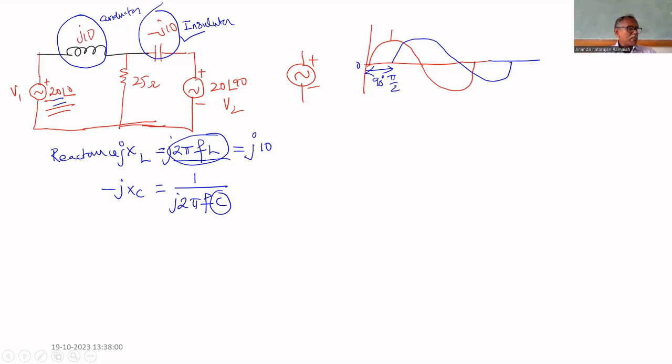Resistance, you know, will resist the flow of current. For AC, its behavior is also like resistance. A pure inductor means there will be a phase shift, a lagging current. A capacitor means there will be a leading current. But if a combination is there, we cannot say pure lagging or pure leading. It will be a combination of all.